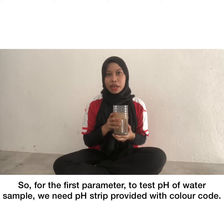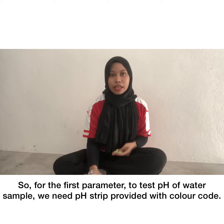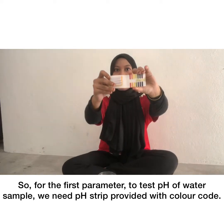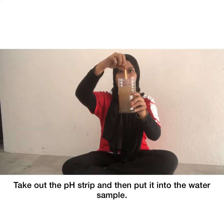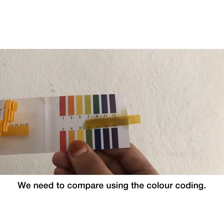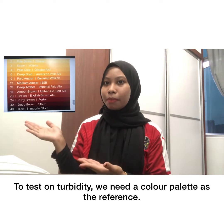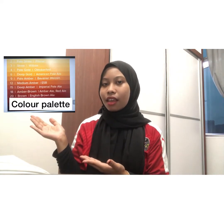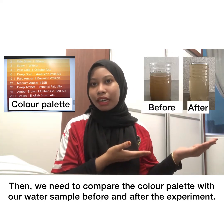So for the first parameter, to test the pH of the water sample, we need the pH strip provided. Take out the pH strip, and then we put it inside the water sample. We need to compare the color coding. To test turbidity, first we need the color palette as a reference. Then we compare the color palette and our water sample before and after.